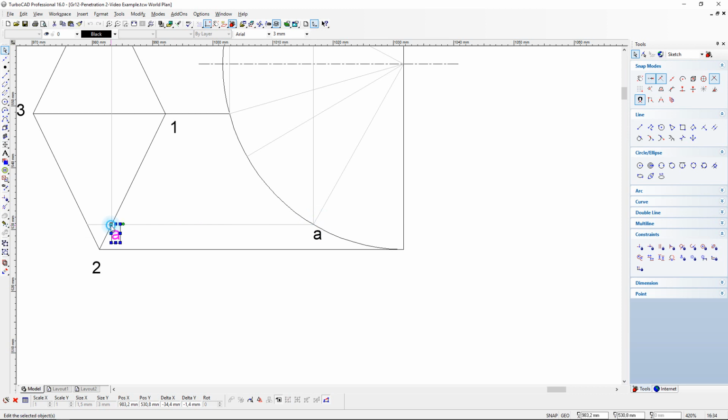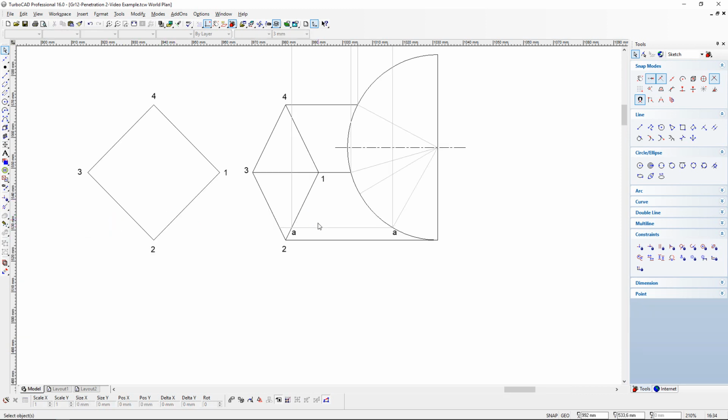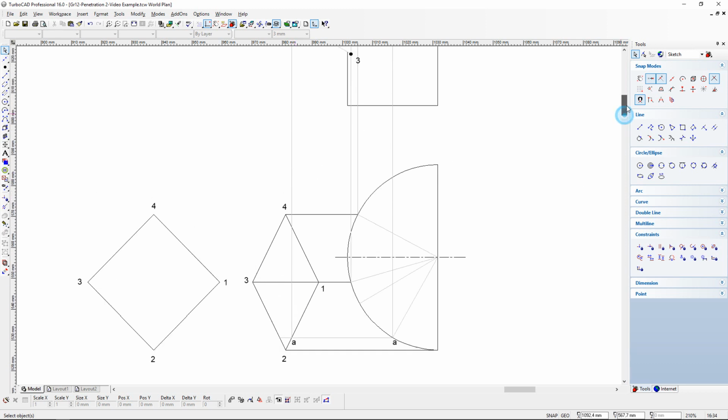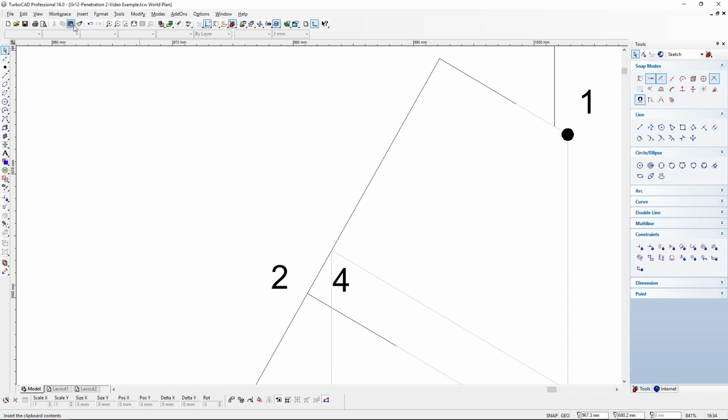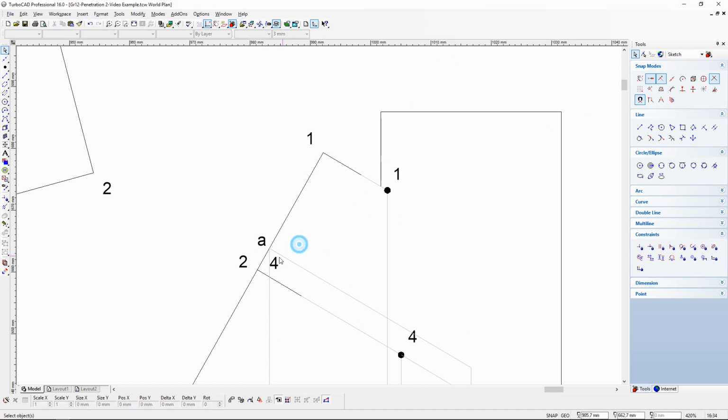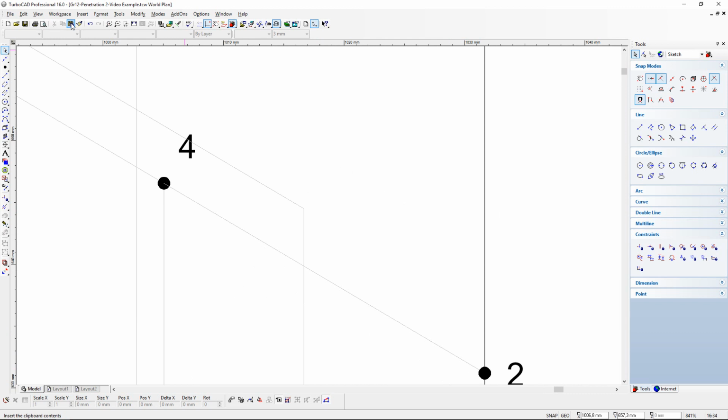and I'm going to show you that A is projected onto this side, side 1, 2, and then we projected it straight up to the front view. That will give me then A right here on the side 1, 2 of my front view, and then A follows down with this line all the way to here, and we complete the loop. So that is A, and we can plot the dot for A.